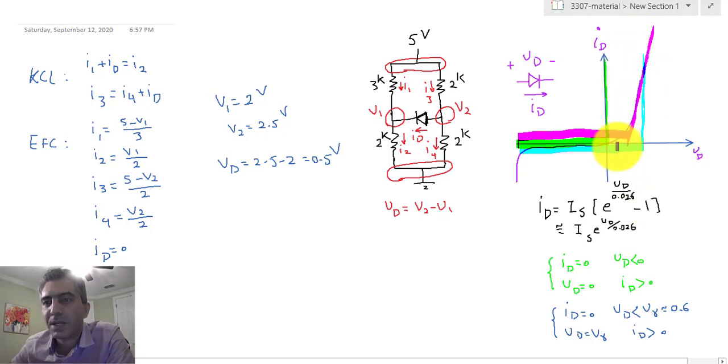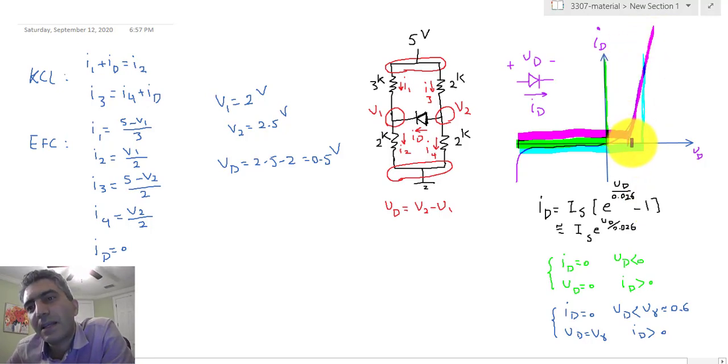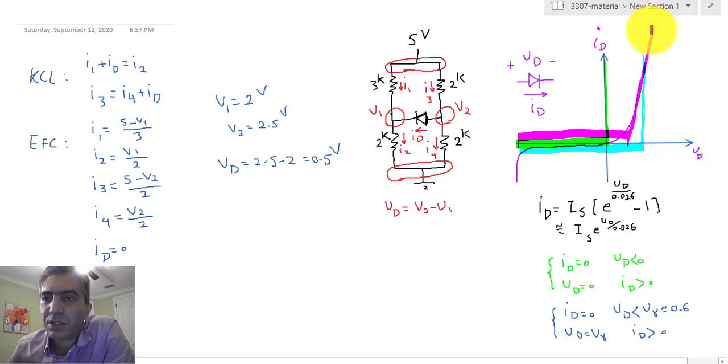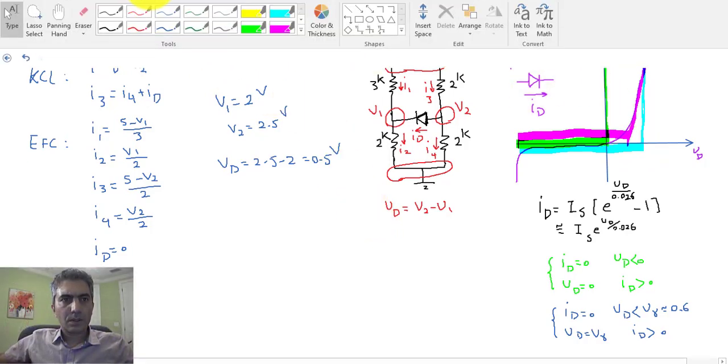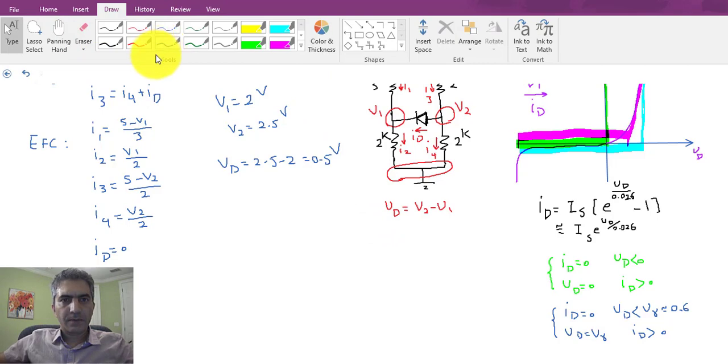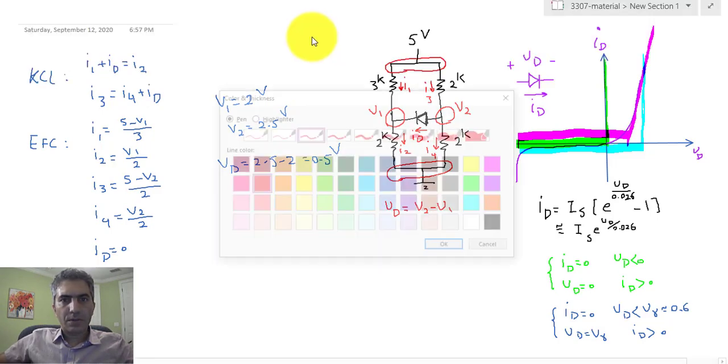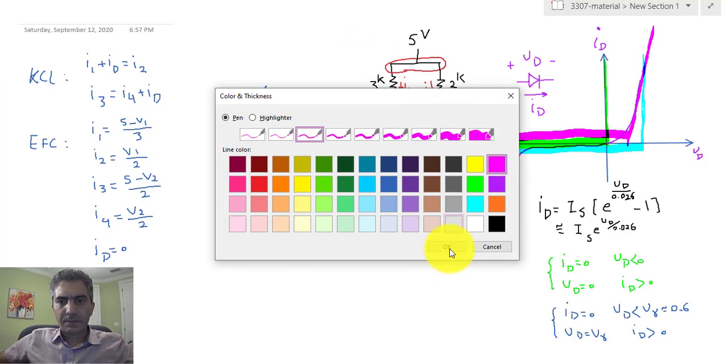So we are basically not saying that the diode, when it turns on, turns into just a straight line or a short circuit or a constant voltage for that matter. The voltage actually changes as the current changes. So it's as if the equation changes to something like this.